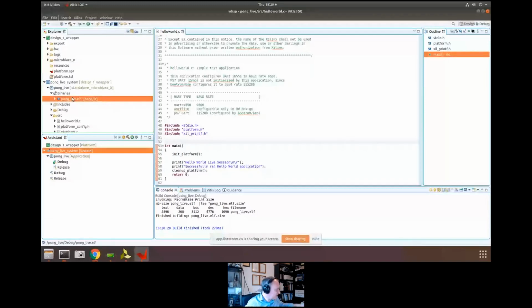But what we need to do first is make sure our board's correctly set up. So if I include this over my camera, obviously we need to connect it for the power and for the UART. With the board turned off, jumper 1, I think it is jumper 1, put the jumper 1 in the position for the JTAG boot. So it goes across the two innermost pins, and then we can turn that on, and you should see maybe just the power light up in the corner, because there's nothing there, it's waiting to boot from JTAG. So we're going to turn that on, connect it in, and leave it to boot from JTAG.